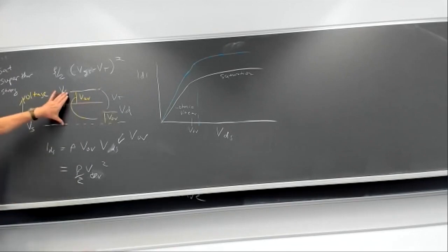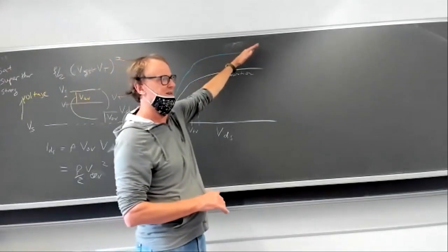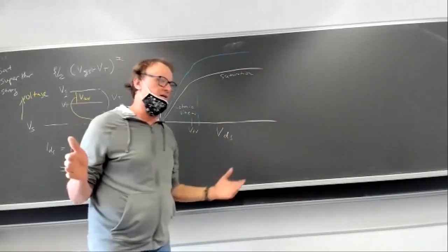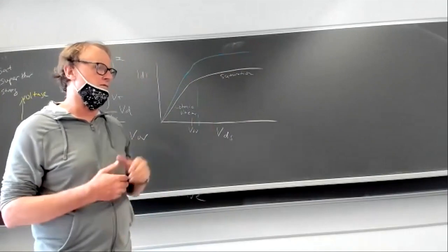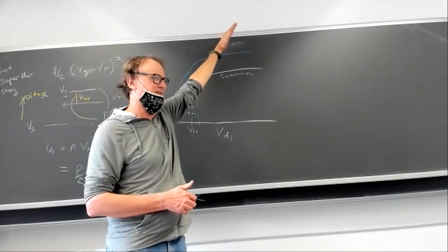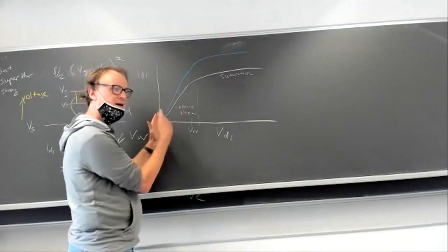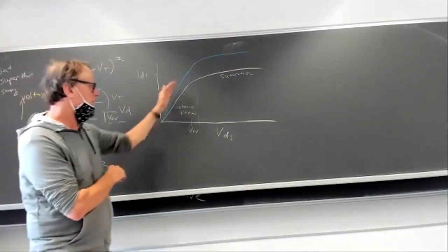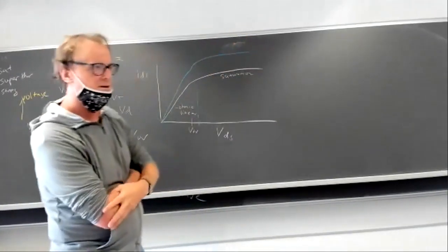See, the bigger the gate source voltage is, the bigger the voltage that you saturate at. That's what happens above threshold, right? So if you put a big gate source voltage, like 4 volts, then the overdrive is going to be like 3 volts. The transistor will be linear for about 3 volts of drain source voltage. In subthreshold, it all happens within 100 millivolts or so. It's a different mechanism, right? Giacomo will show you next week. But above threshold, the harder you turn on the transistor, the longer the region that is linear.